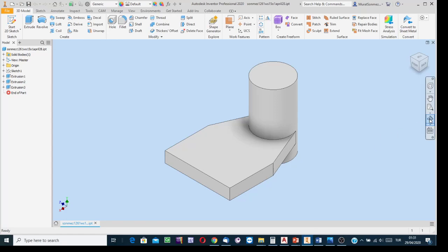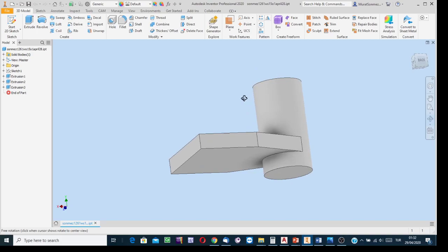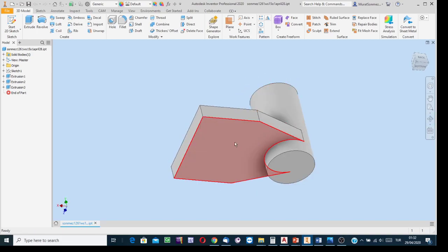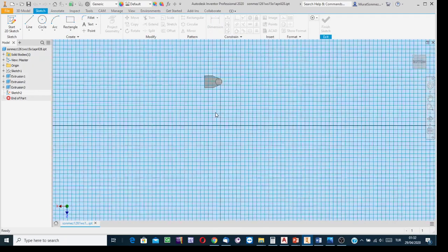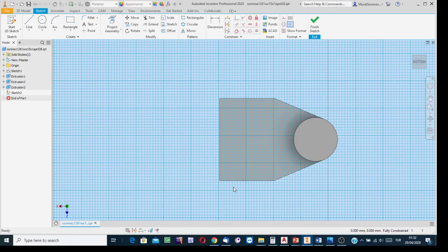I know that it is based at the bottom side, so rotate it and see the bottom side surface of this part. And then on this surface, take a sketch, right click, new sketch. And then create the sketch. The sketch is to be the base of the rectangular extension.